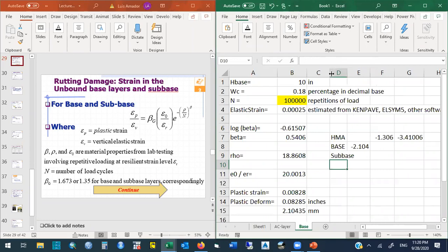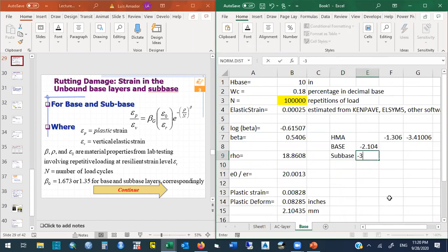Oh yes, exactly. Because before I was ignoring the fact that it's supported over a base. And if there's a sub base and the sub base is going down as well, just imagine that's the sub base, I'm just making up a number, you also need to consider that in here. So each layer will suffer a permanent deformation, and the surface is the accumulation of all of them.